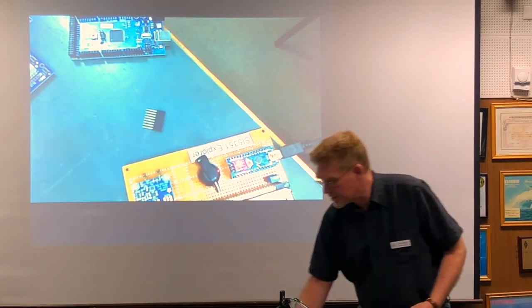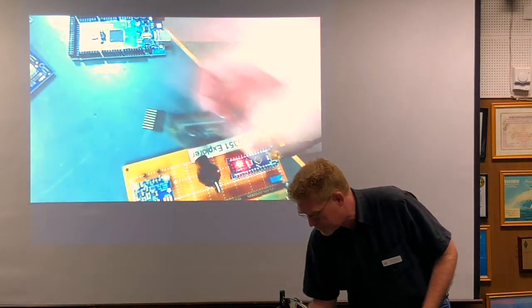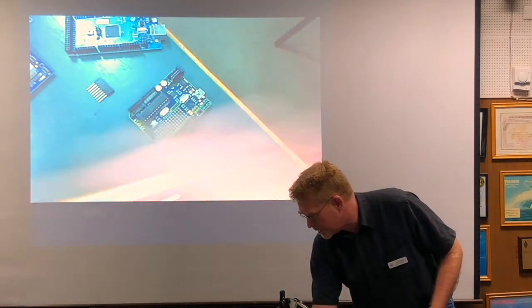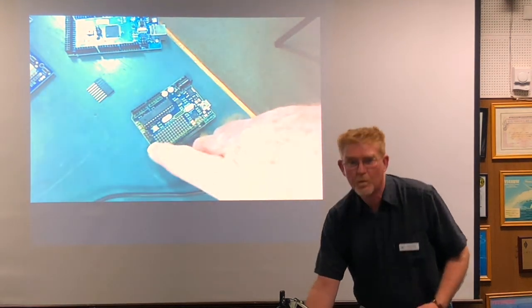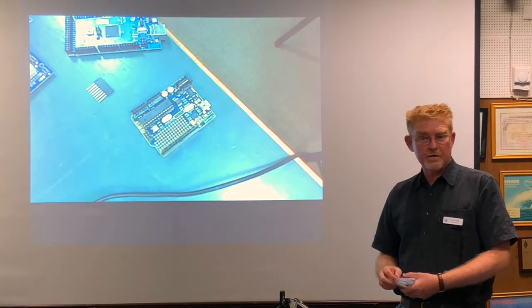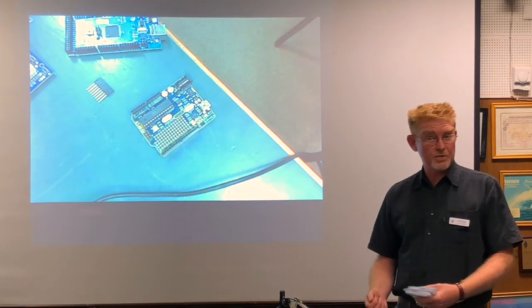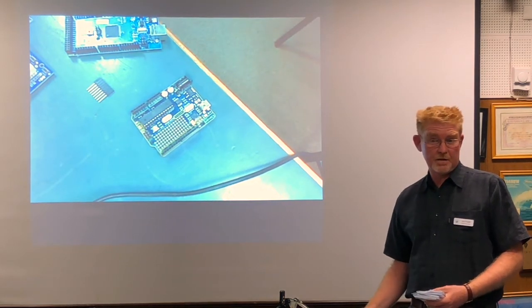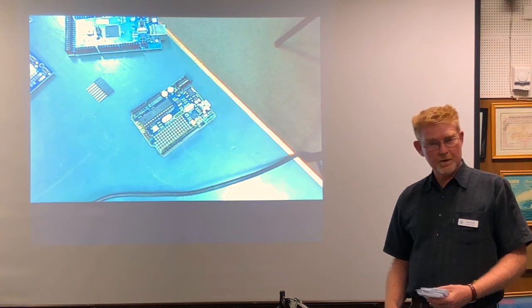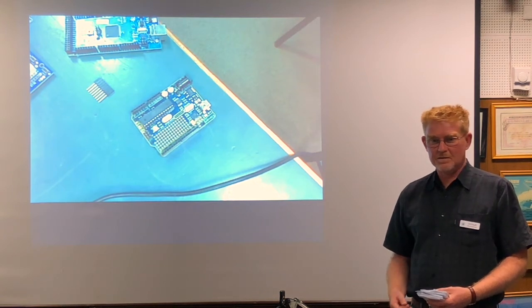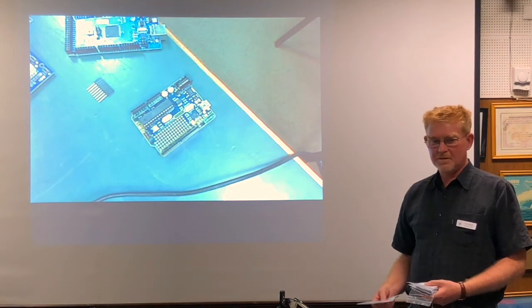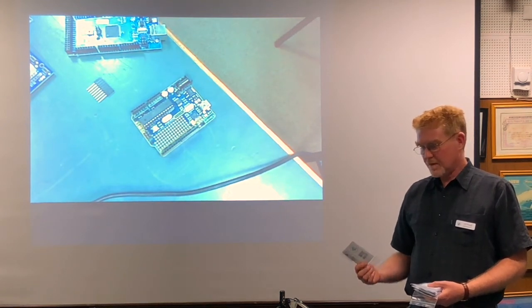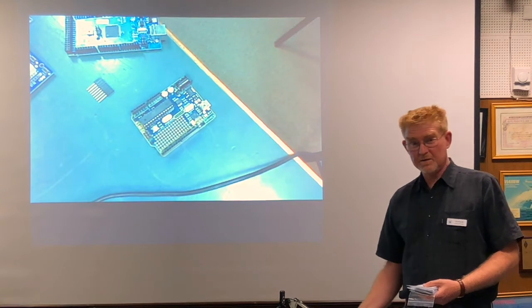Most Arduinos have this funny little 6-pin header where you can use the Arduino in-circuit programmer or a sketch on another Arduino to re-download the bootloader. It's annoying, but you do it a couple of times, you get over it. But I've never damaged an Arduino, one of the AVR ones, by software.